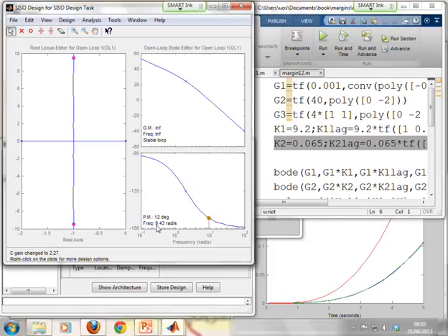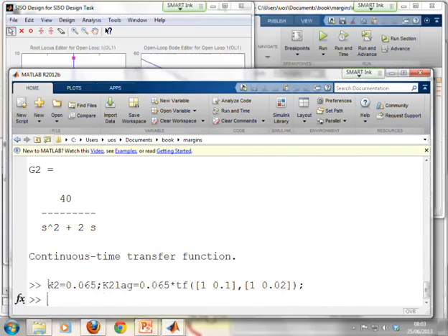Okay, and because I now need a phase rotation of about 48 degrees, that's going to be a beta of around 8. So what you need to remember is this number, 9.43, and a beta of about 8. So let's go back to the MATLAB command window, and let's enter this compensator. I can go back to the command I used before and just change the numbers, then we'll see the structure. So it's K2 lead, and with the frequency we now said was 9.75.